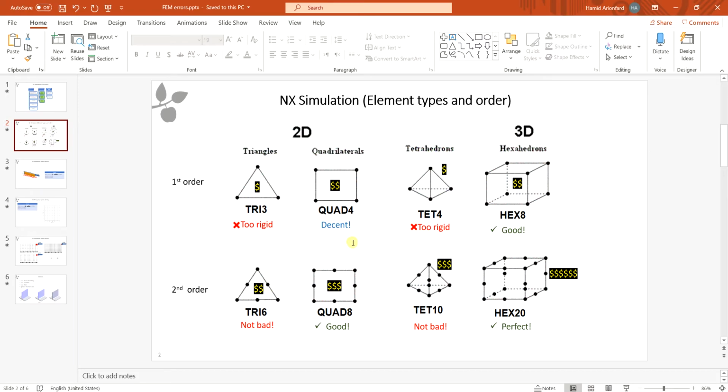There is another problem you need to know, which is that you better avoid using only one quad element in a part. So if you want to model thickness of your part, you should avoid using only one element. Otherwise, you won't get the accurate deformation.